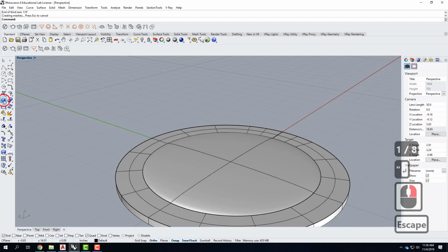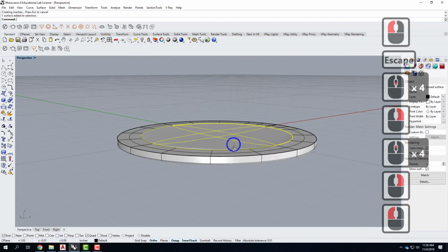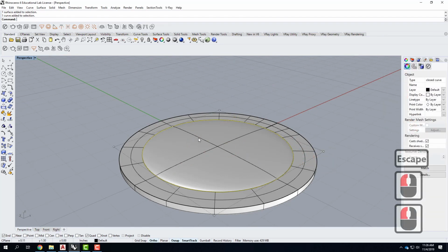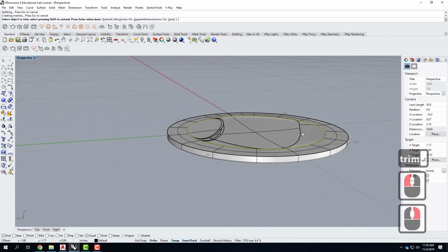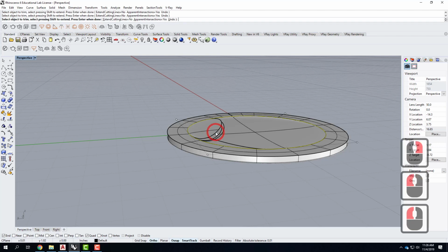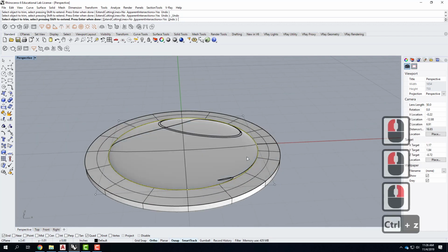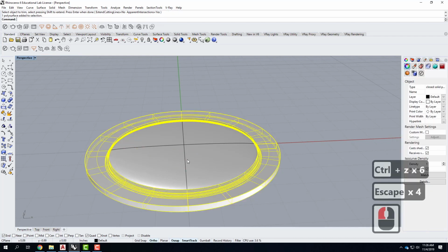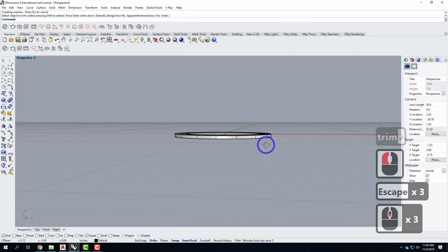It's an ellipsoid. It's underneath the cube here. It's that one. And so we can see that it has a slight little bit of an arc to it on this side. I don't need the whole arc, though. I don't need it on the back side. I'd rather keep that flat. So I'll select the curve that I had here, and I'll trim the back half off. At least I hope I'll trim the back half off. Oops, it doesn't like me. I'll try that one more time. Let me use this as a trim. There we go. So I'm just going down with it.